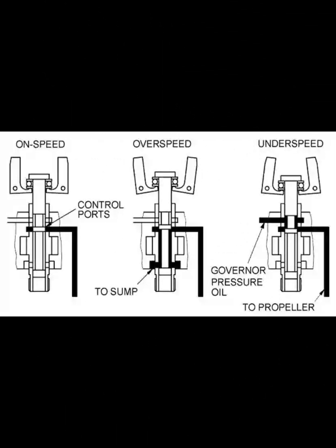What types of systems are used for de-icing propellers? Fluid or electrical. What is the purpose of a slinger ring on some propeller installations? The de-icer fluid is ejected from a nozzle into a U-shaped channel attached aft of the propeller.